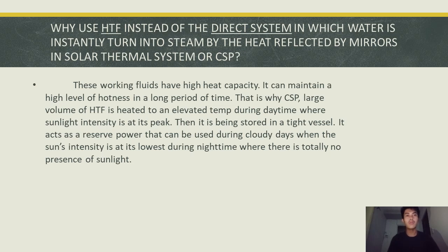And even if a fluid is used at a continuous temperature close to its recommended maximum fluid operating limit, there is a point to take into consideration. The thermal degradation rate is not a linear function versus temperature. As the bulk fluid temperature approaches the fluid's maximum recommended temperature, the degradation rate soars asymptotically.